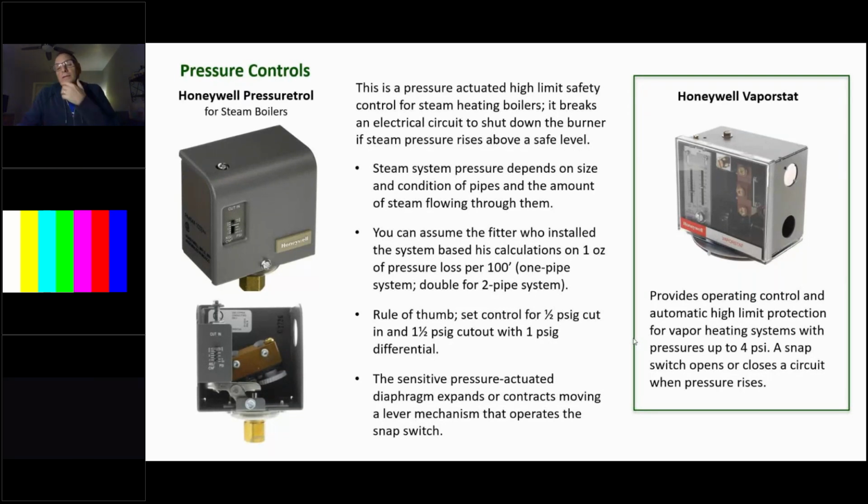Otherwise, if you run into that and they're having problems with the radiators with the vapor style valves on them, it's probably a good idea to change them all over to standard radiator valves. You can still run the system in vapor. That's not a big deal. But it'd probably be a good idea to change those out.